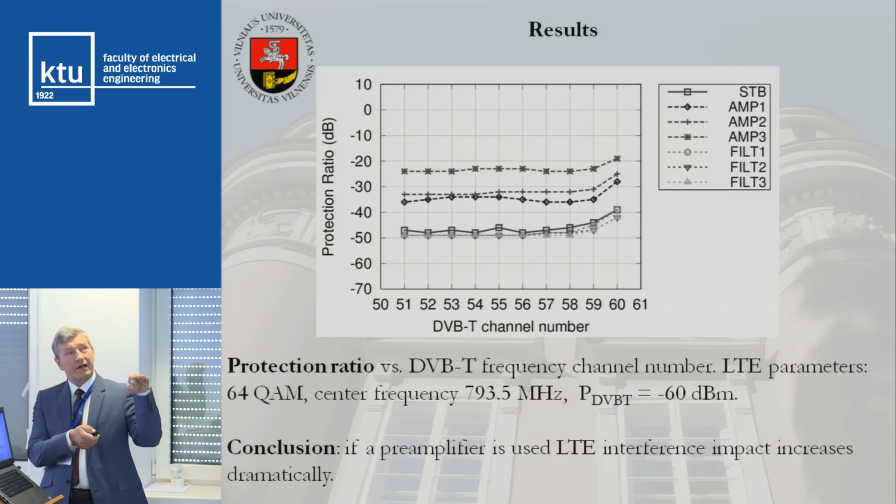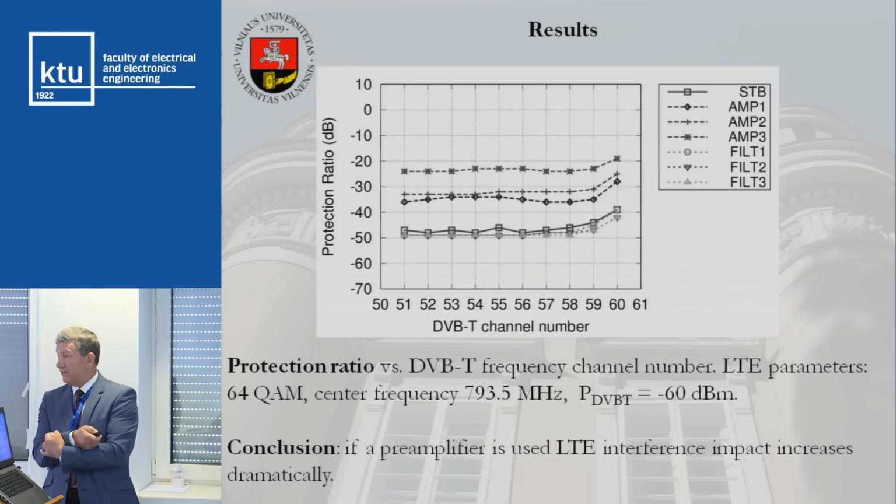It gives us a higher protection ratio when compared with the solid line, which corresponds to the case when no amplifier and no filter are used. And when connecting filters, we can only slightly improve reception conditions. So really it is only a waste of money.